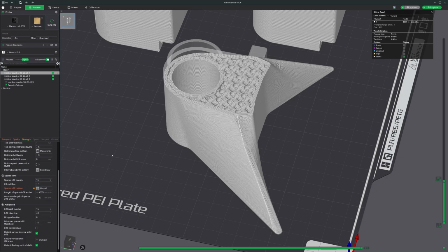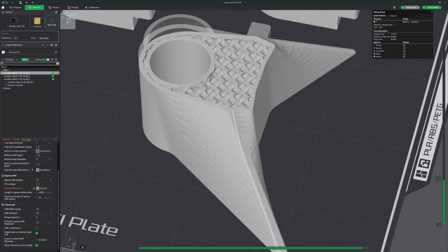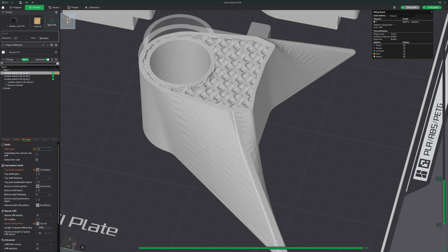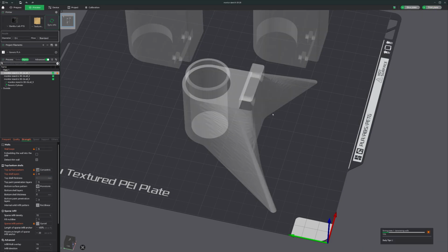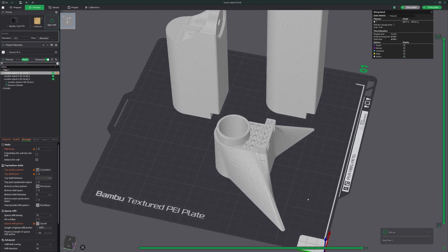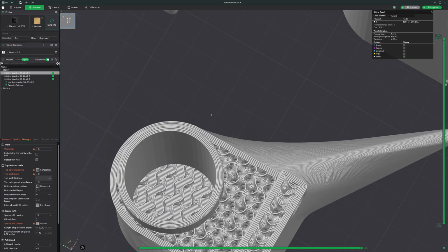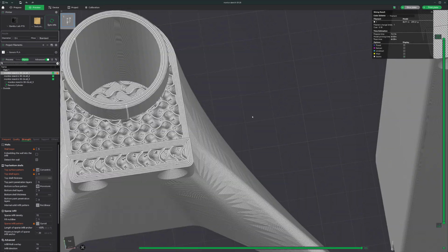There is a cool trick I'm going to show you right now, if you're ever working on a part that you want to be able to see the infill. So you can do a trick here. Go up to your walls and turn this to a 0. And then whenever you prepare the top layers of your part, you'll notice they won't have a top surface, so you can see your infill. It's kind of a neat little thing you can do, and why some of these other ones exist.